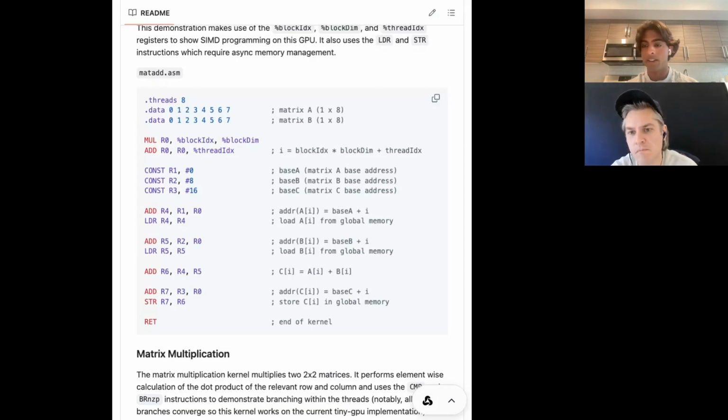And the question is, when you run 8 of these threads, let's say we now have 8 of these exact same pieces of code running in our GPU. Let's just say somehow we accomplished that. The question is, how do you actually get each of these threads to do something slightly different? They're all running the same instruction, but you need them to perform it on separate data, like the different elements of the matrix. So somehow in the actual hardware of the GPU, you need each little area that's executing one of these kernel codes to know something about which thread it's executing. Is it executing the 0th thread? Is it executing the 2nd thread, or whatever?